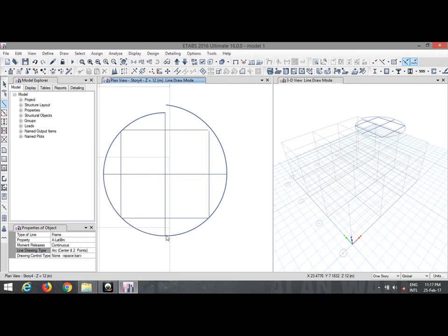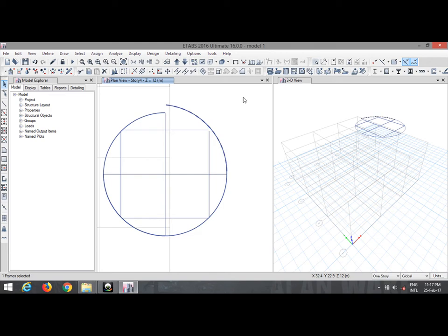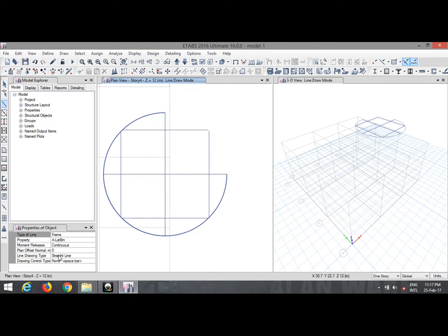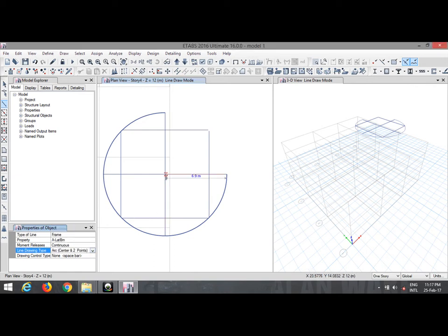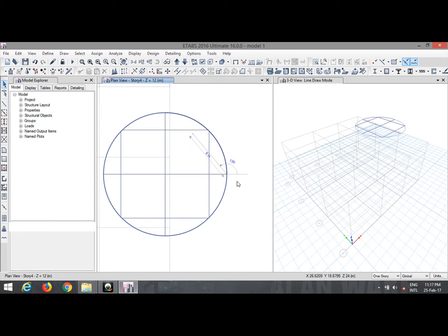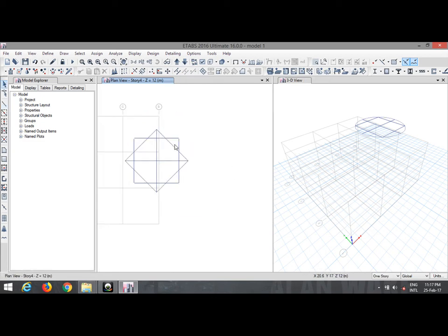So here you can clearly see that we have assigned. Now delete this beam and once again reassign the beam at the correct points. So we choose exactly at 7 meters and now draw the beam. So now we have drawn the circular beams. Now we need to intersect at every node.